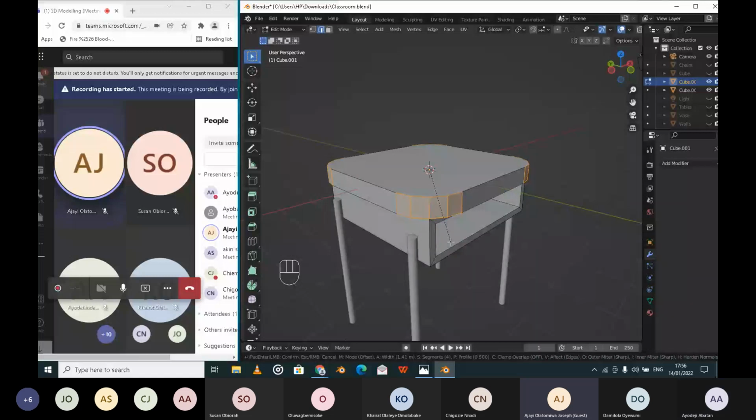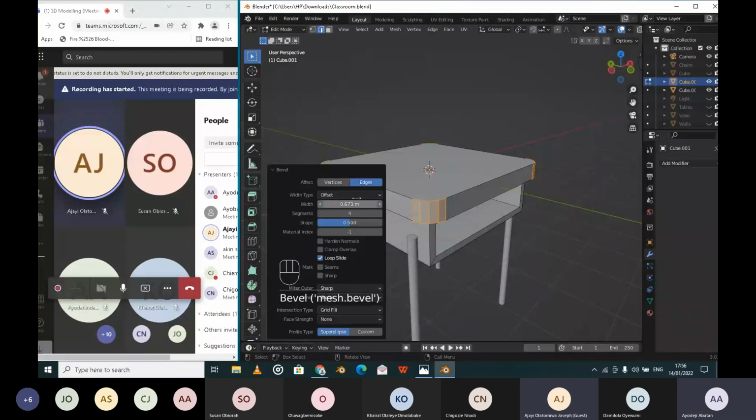Do you understand that? You can do it to the most and turn the entire thing into a circle, but we don't want to go beyond this place. We want to start dragging it out at this point, the edges. We can simply make the edges curve a bit, and that should do. When the bevel toolkit comes up, you increase the number of segments. The more segments, the more curve-like it appears. But be careful, if you use too many segments, your laptop can crash. So let's stick with something as simple as 4. Do you understand that?